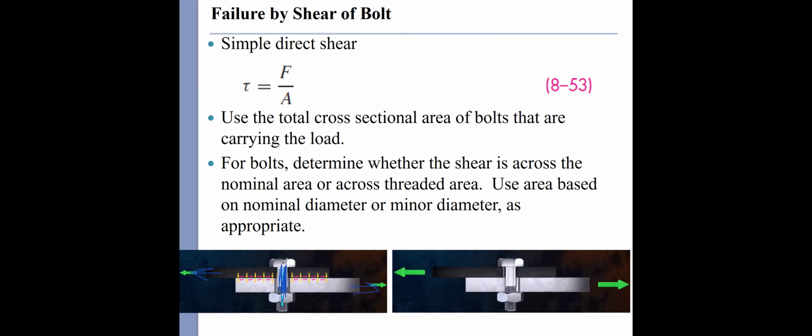The preload creates a friction force between the two members, and this friction force can be regarded as the resistance to the tear or the shear force.